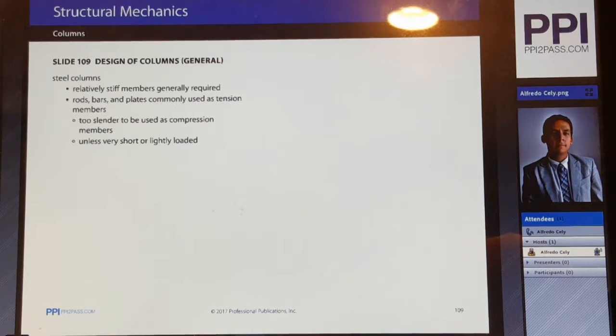For building columns, W shapes with nominal depths of 14 inches or less are commonly used. These sections typically have a relatively square outline shape and are more efficient than most others for carrying compressive loads. Figure 61.1 of CERM shows the cross-section of typical compression members.